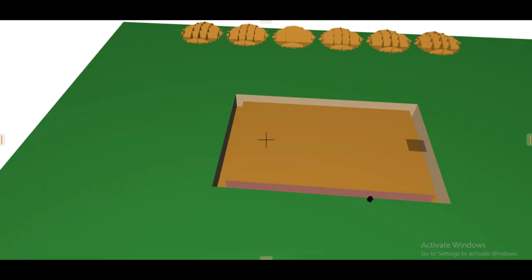And now to demonstrate how to dispose this, remember you have a mini-gut here, which if you multiply by the width and the depth is giving you a volume of soil, which upon excavation must be disposed. So you can do it on site, meaning within the site, whereby you can again reuse them to do backfilling, or off the site, meaning away from the site and you are not intending to use them.